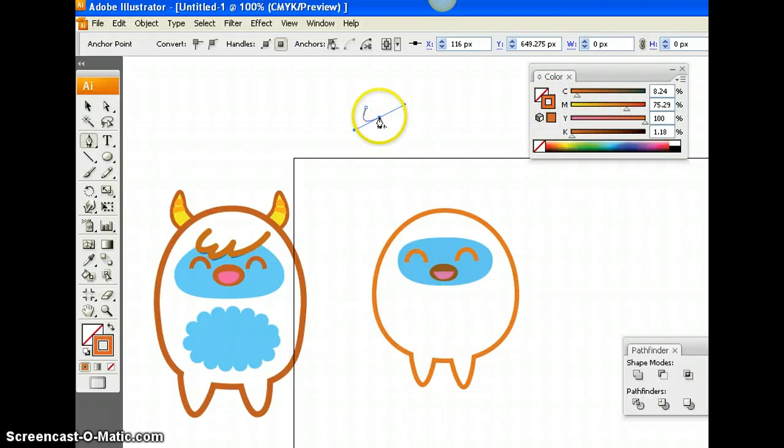Then we go back to here. The next one comes down here, doesn't it? Ooh, I don't want that. Where's that coming from? Control Z. I want it to come down here. Why is it doing that? Now if that's happening to you, Control Z, click on the last point that you drew, go back to the last point, click, and then draw. And that won't happen.